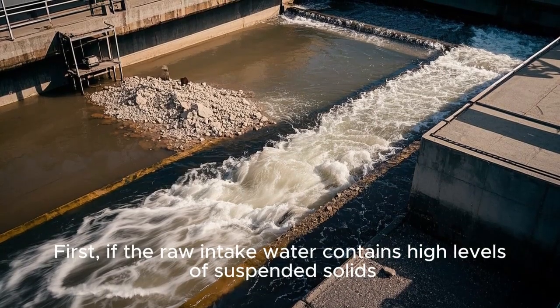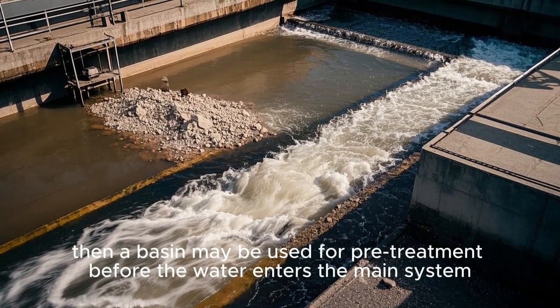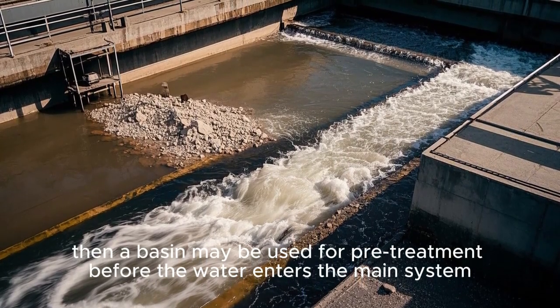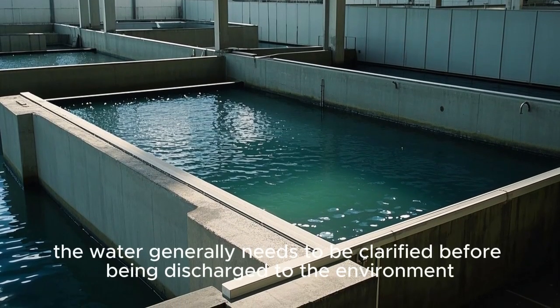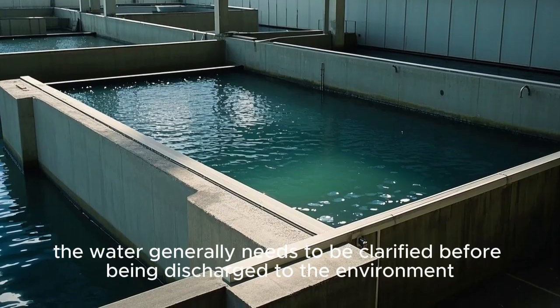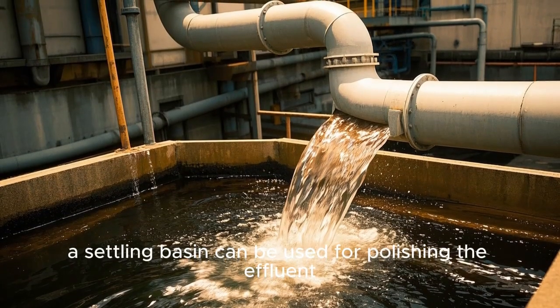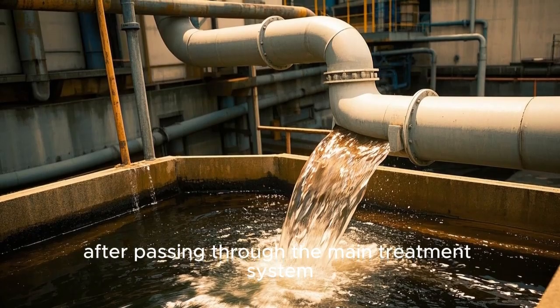First, if the raw intake water contains high levels of suspended solids, then a basin may be used for pretreatment before the water enters the main system. Second, in RAS, the water generally needs to be clarified before being discharged to the environment. Therefore, a settling basin can be used for polishing the effluent after passing through the main treatment system.